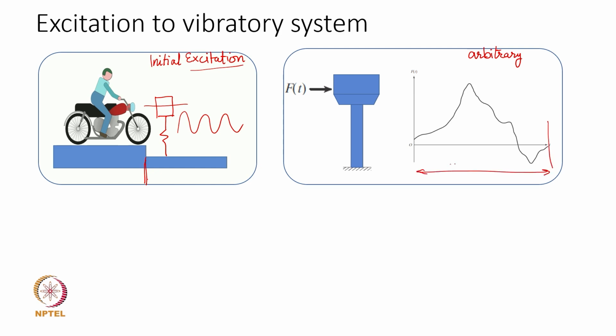This time is not infinitesimally small, it persists for a reasonable period of time, and it may or may not be captured using some mathematical form, and we discussed how a numerical approach can help us evaluate the response to such an arbitrary excitation. Essentially, this arbitrary excitation case was stripped into the case of initial perturbation by considering a series of such initial excitations through the impulses. Okay.